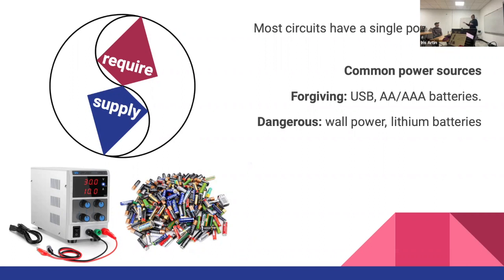And so this takes us back to the earlier thing about short circuits, because a short circuit lets energy move very quickly through the battery and out of the battery and back into the battery on the other side. A short circuit can overheat the battery. So if there was something as simple as a loose wire somewhere inside the phone that would short circuit the battery, that is one way that you can set the lithium battery on fire.